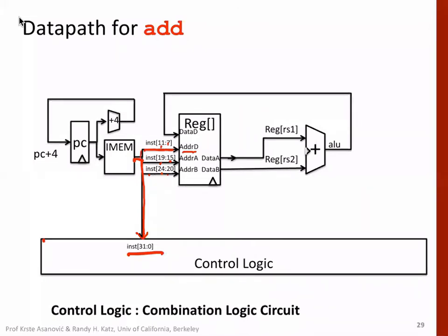These bits will go to these ports. Now we'll have to see what will be next here. Now this will be enabled. So this is the register write enable signal that we have seen. In case of reading, this will be 0. And then two values will be read from the register, right? So this will happen in the first phase, as soon as the values are available here.